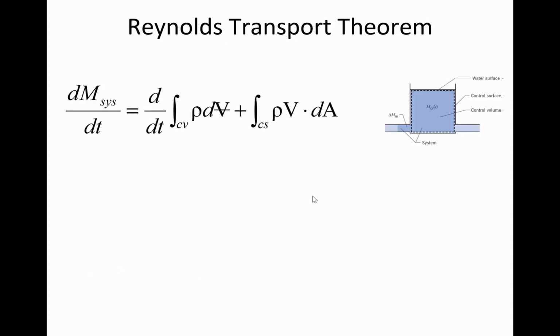Okay. So here's the Reynolds transport theorem, and you may remember seeing this figure in our last class meeting where what we were doing was keeping track of some control volume that was essentially the volume inside of control surfaces. And the control surfaces were those outside locations where we were tracking the flow in and flow out of a system.